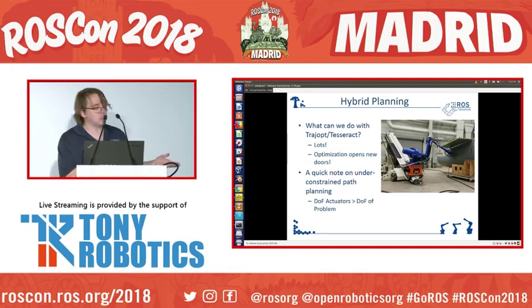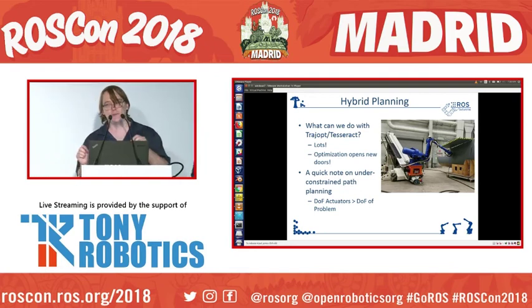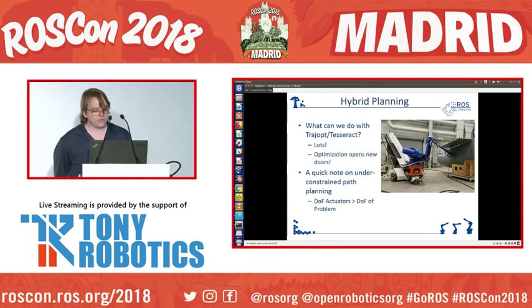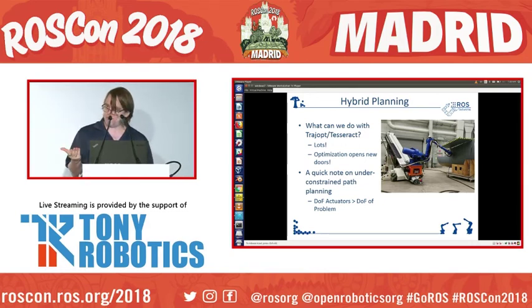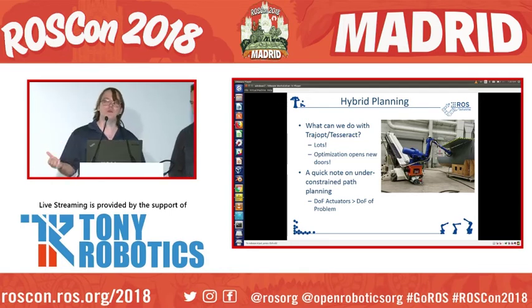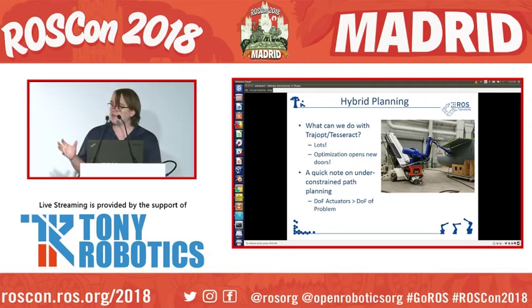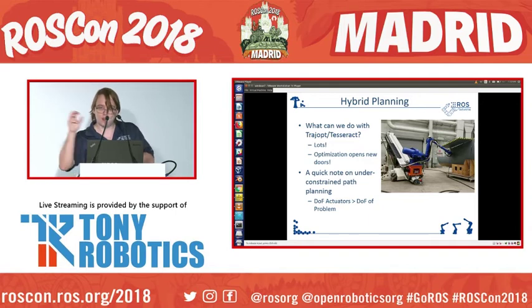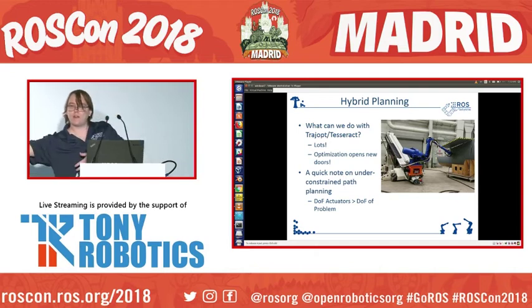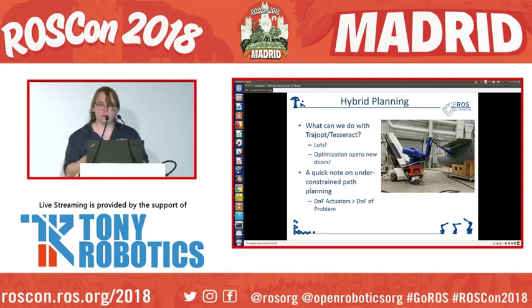Like Levi mentioned earlier, we usually get a path and then try to massage it afterwards to make it achievable by real robots. With optimization, we can do it in situ, if you will. If you have a rail like on this robot and it's really slow compared to the rest of the system, we can use the optimization to allow the robot to take up slop in a linear trajectory. Like you want to maintain a constant speed, and the rail accelerates really slowly. Well, the arm can shoot out in front, and then the rail can catch up. It's a really awesome opportunity to solve more problems and make them more reasonable.